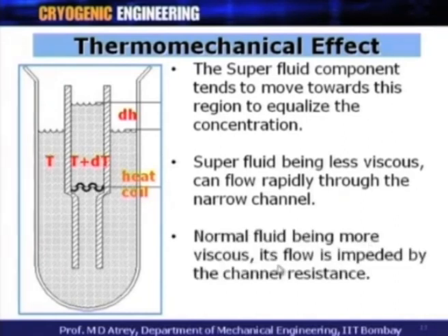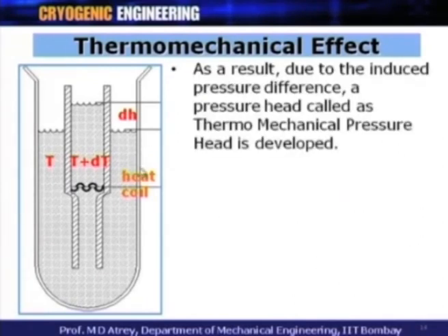Normal fluid being more viscous, its flow is impeded by the channel resistance. As a result, heating here will induce a kind of flow, and as soon as the flow starts, it will induce a pressure difference. Due to this induced pressure difference, we get a pressure head, which we can call the thermomechanical pressure head, because it is induced because of this temperature difference.